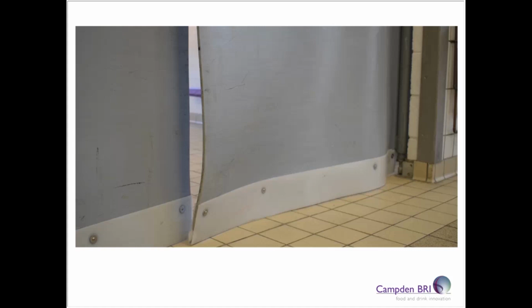They should be controlled and well sealed. And now the seals are very important to consider, because the seal is touching the floor in this example, and if there's any contamination that gets in between the seal and the door, this could commonly be a source of the listeria. So it could be then spreading each time you open and close the door, and then you walk that through the factory facility. So consider the seals and how they are in contact with the floor, how wet they may be, and can you maintain them and clean them sufficiently.